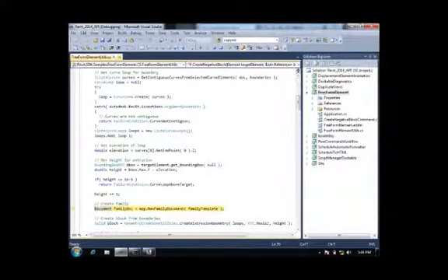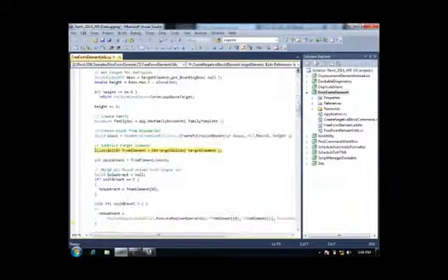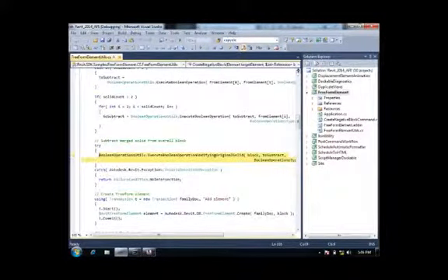In order to create the new element, we need to open a family document. We'll use a generic model template, then create the extrusion geometry from our closed loop, get the target solids, make sure that we have one single target solid to start out from. We want to create a new freeform element in the family document that we just set up.